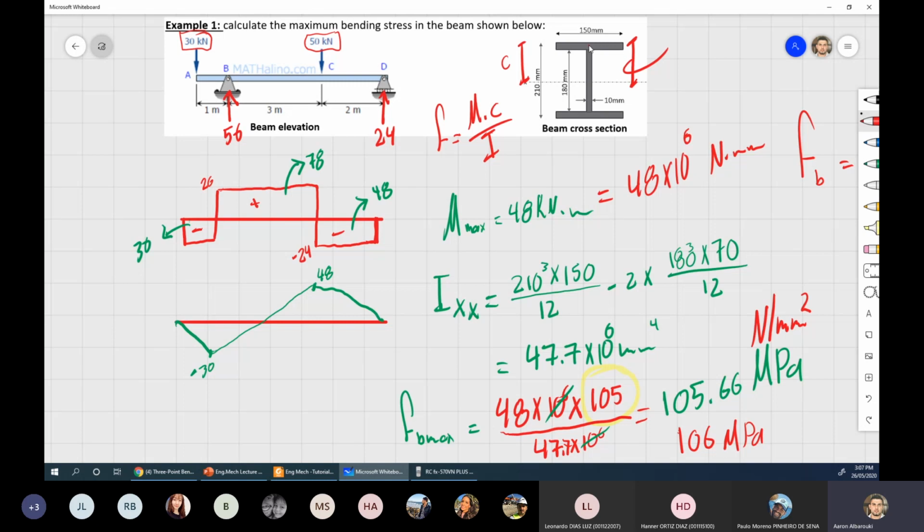Think of the particles of steel in here. They stay too hot, but the ones on the outside cool down, and when they cool down, they form solid material, whereas the inside here is still not very solid and still hot. When this tries to relax in the center, it can't because everything around it has set already. So this will cause these particles in the center to be pressured or confined. We call this process residual stresses.